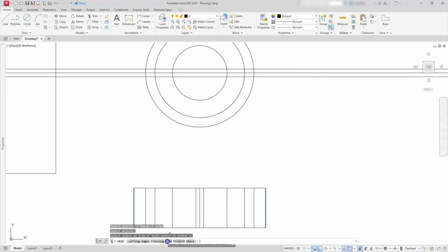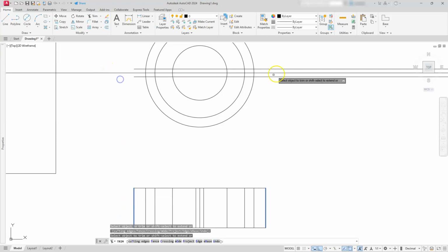So now I'm going to go to mode. And when I switch to mode, right now we're on the quick mode. I'm going to go to the standard mode. And then when I select the cutting line, I get also another one here, which is the edge. So with that, I can select the edge and it's set to no extend. I'm going to change this to extend now. So when I go to extend, now you're going to see that these cutting edges now extend all the way up here to the top. So when I trim these lines, they will now extend and trim here.